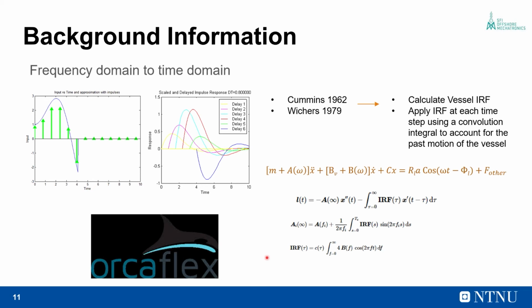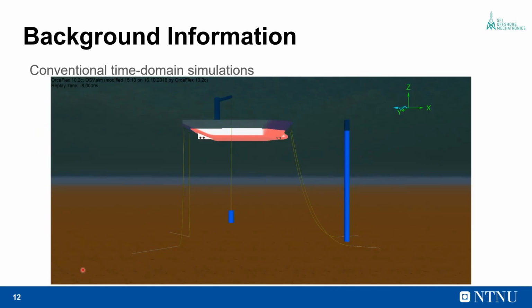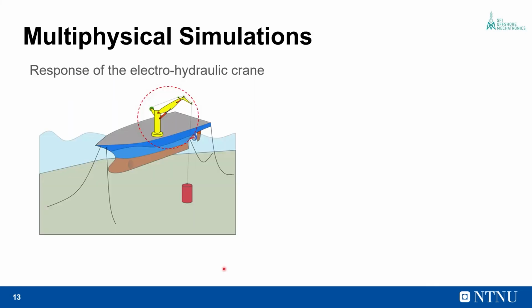So let's look at an OrcaFlex simulation now for the case that we are considering. So the simulation is in progress. Here I have previously carried out the frequency domain analysis for the same vessel in ANSYS Aqwa and imported that data into OrcaFlex. And then I have attached mooring lines and the subsea loads inside OrcaFlex, and all these are basically Morison elements. And this is how the simulation progresses.